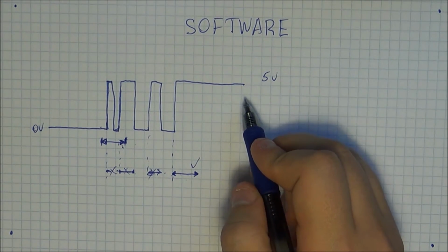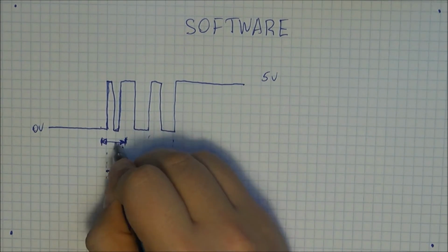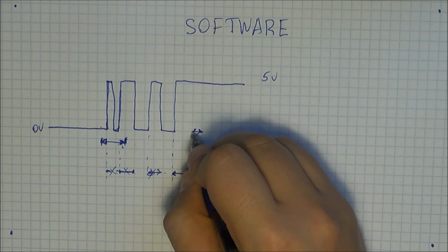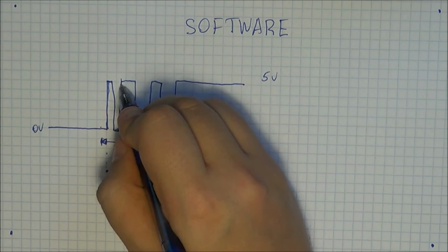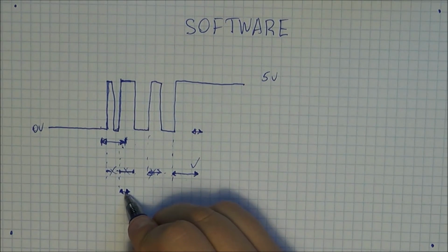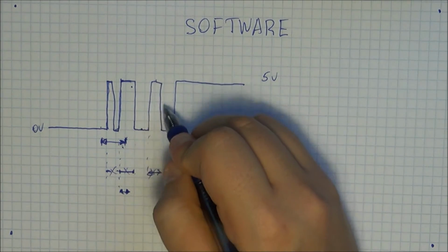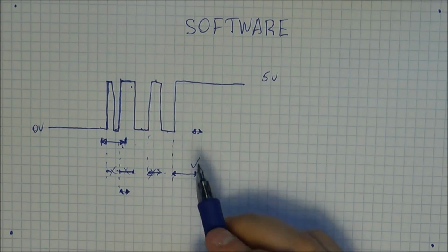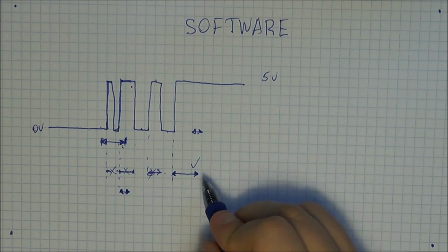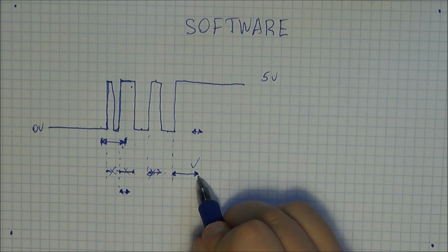So as I mentioned in the main tutorial, if you make it too short, so for example, instead of this, you select something like 1 cell, you may get a positive read somewhere here, right? Because as soon as you get this short high, your Arduino will confirm that you did get a high, but then it will go back to low and switch back to high, low, and high. So you have to really be careful with what's the time of your setting and what's your certainty. That basically determines the length of your checking time.